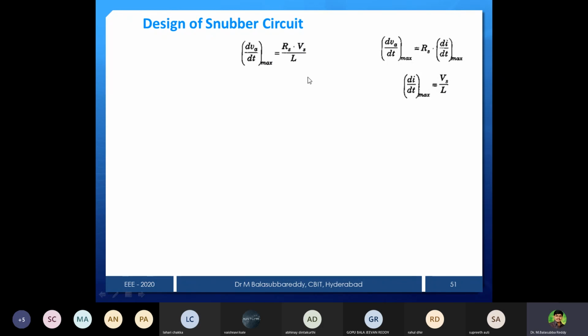This one. And from this, what can I write for Rs? With simplification, Rs is equal to L by Vs into dV by dt max. That much resistance you have to place based on your dV by dt rating.